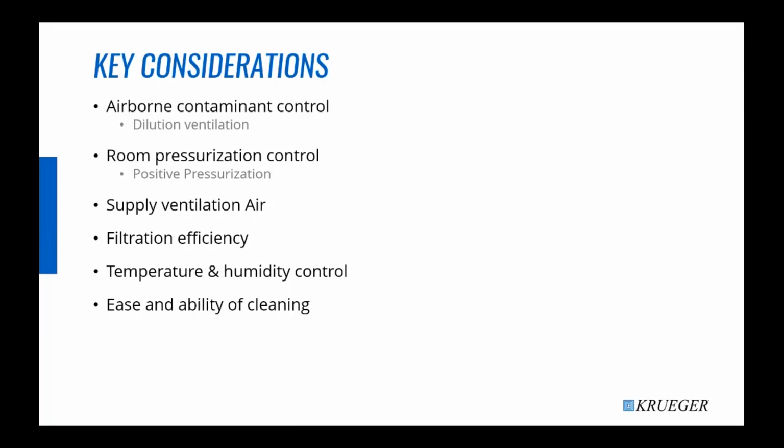Because we do have occupants in the space, we do need to get some supply air ventilation into the space as well. The standard also identifies filtration requirements for contaminant removal. And these are indoor spaces, so temperature and humidity control will be important as well. Finally, air devices selected for an operating room should be suitable for withstanding regular cleanings and wipe downs. We want to make sure the diffusers are accessible and cleanable, providing access to the plenum as needed for regular cleaning.